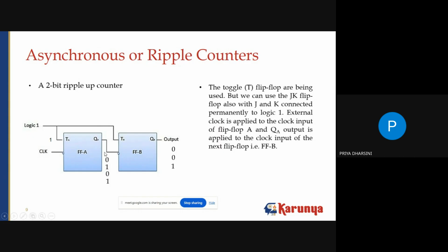So from logic 0 to 1, it is in the positive direction. So this particular clock will not be triggered because you are giving it to a bubble. Bubble means a negative trigger only will be activated. So from 0 to 1, it will not activate. So whatever data was already previously present, the same data will remain. So what did you already have? 1 was stored, the same 1 will be stored.